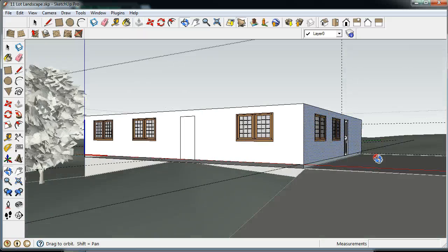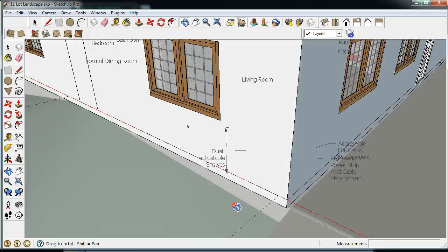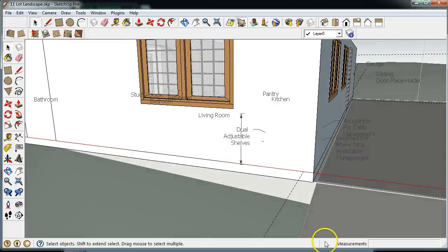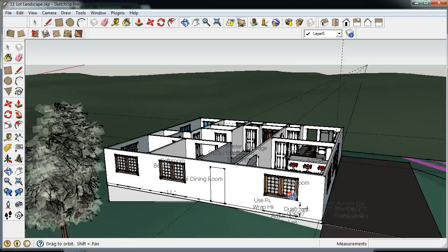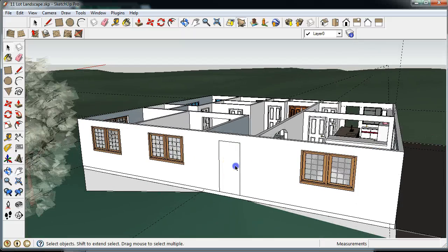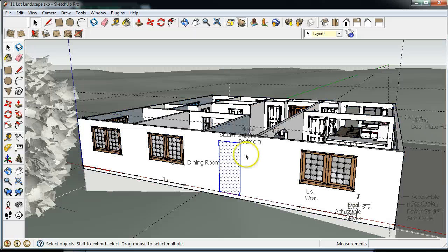Come to the front. It's hollow underneath there, so you're going to create another rectangle right over top to seal that box. Alright, so there is your house on top of the foundation, and then when you click out of the component, the floor will be part of the actual component. And if it messes things up like it did in the front here, you can edit the component, like this part right here, and let's delete that face.